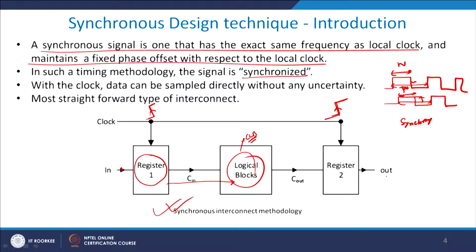Now, with the clock, as I discussed with you, data can be sampled directly without any uncertainty, and so this is the most straightforward, simplest interconnect design for using your synchronous digital technique, and it is pretty easy to implement also. There are also two other important designs. One is known as mesochronous and another is known as plesiochronous.